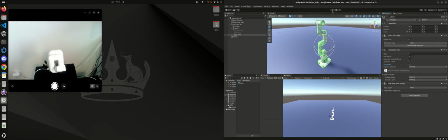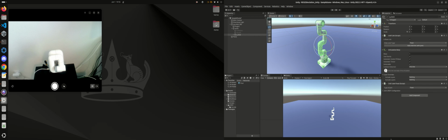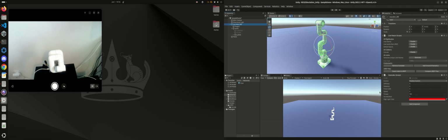This means that when we repeat the process and click play, our robot only moves the different articulations, the different joints. But this movement is not a controlled movement. To solve this problem, we need to modify the values of stiffness and damping, the force limit, the speed, the torque and the acceleration.